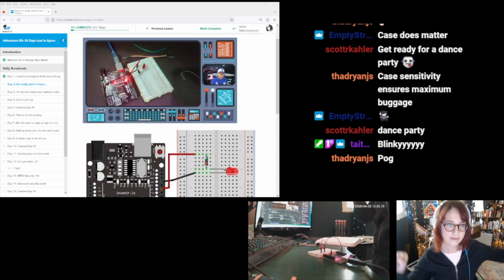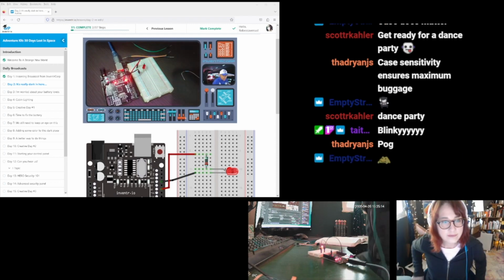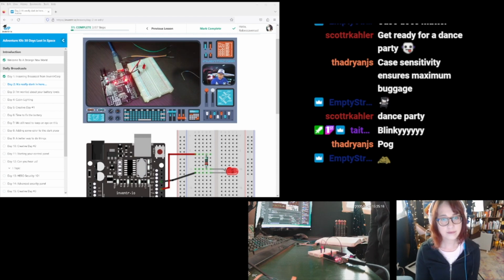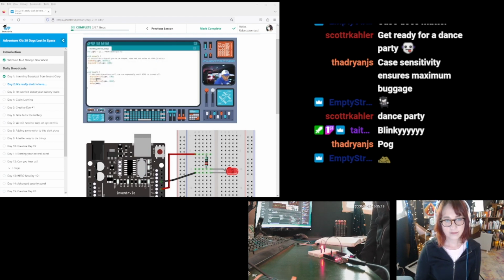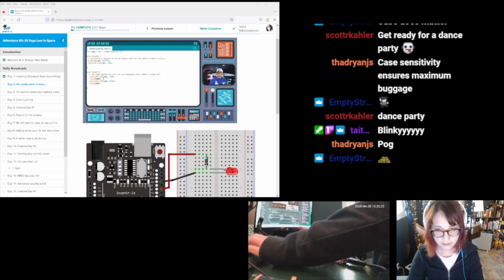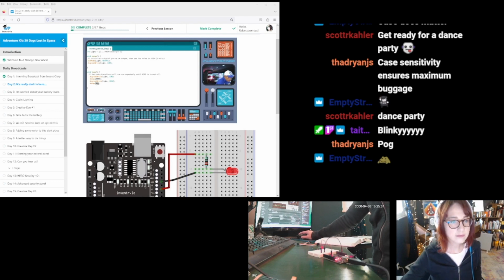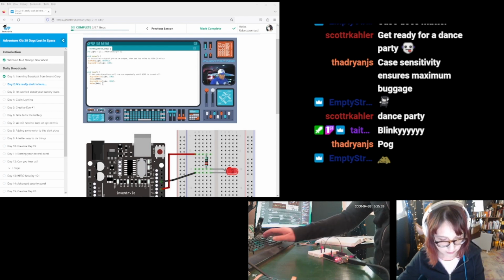And you can see that we can customize this in any way that we might like. So for example, we might say, what I'd really like is for the light to be off for 2 seconds. And so I could do that by simply changing the value that I sent to delay to 2,000. So that would be 2 seconds. And then I might say, I really only want the light to flash for a brief period of time. So let's change it to 1/10 of a second, or 100 milliseconds. Okay, so that's my new code.